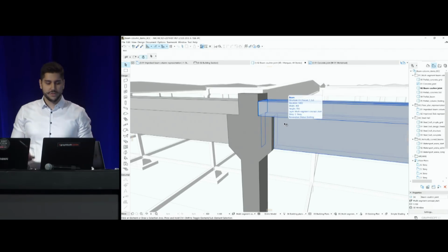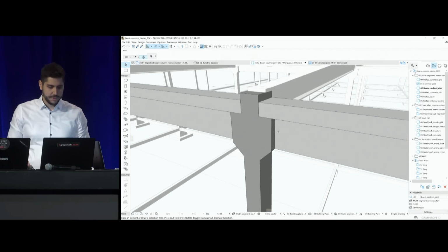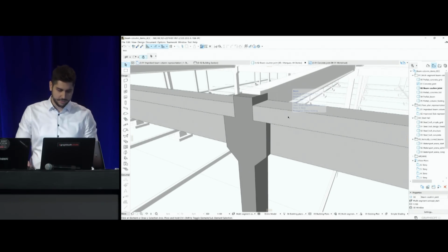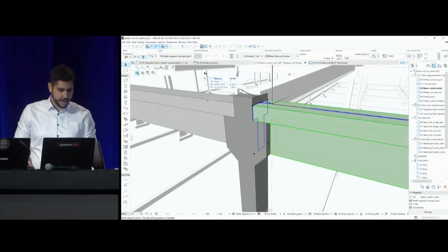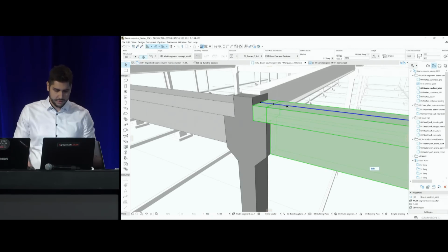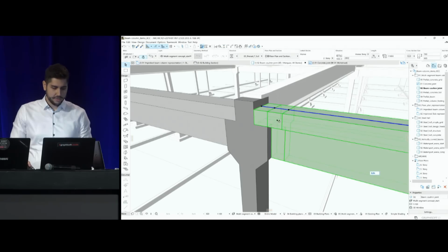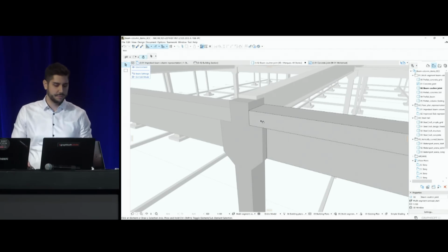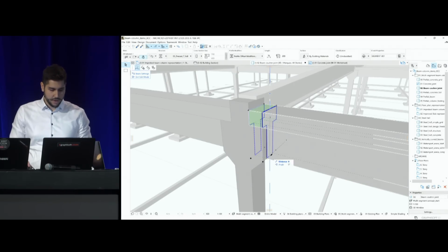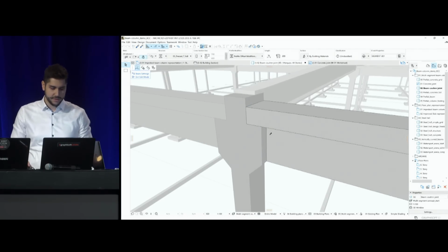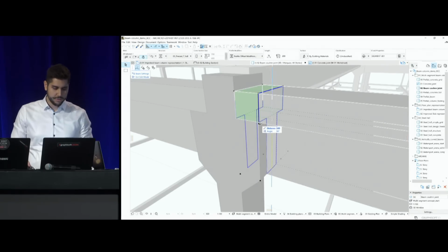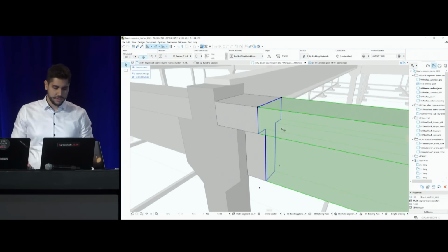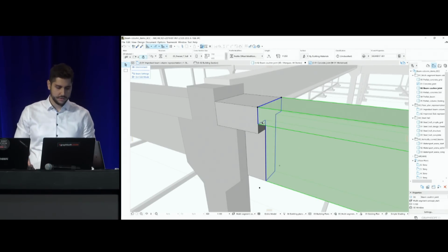Now, so far this is all right, but let's take a look at the beam and make it a proper ending as well. Similar to the columns, I can add segments to it by clicking on the reference line. And right now, as you can see, it looks correct, but this is only a result of the priority-based connections at the support. So since we are using parametric complex profiles, I can get rid of the girder depth or just reduce it. And since I do not need a stronger support throughout the beam, I can make it a little bit thinner on the top.